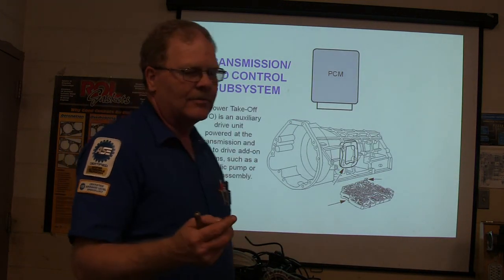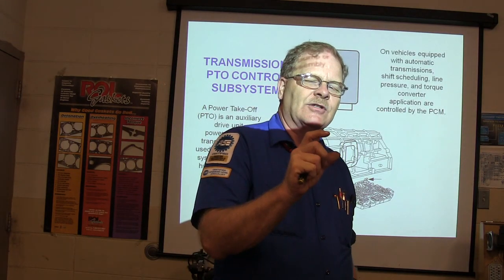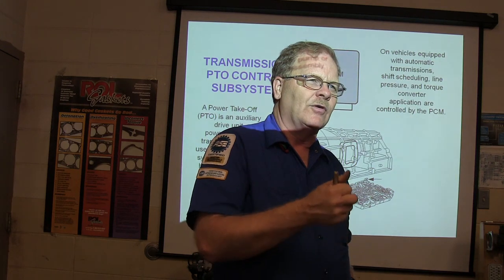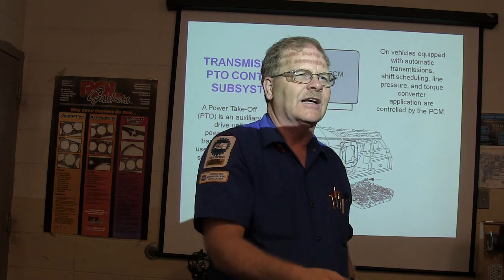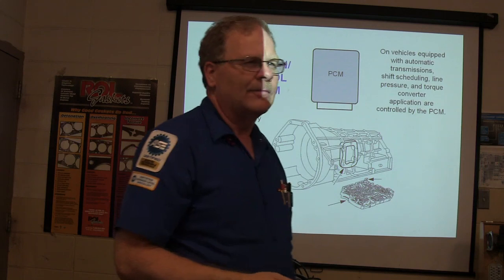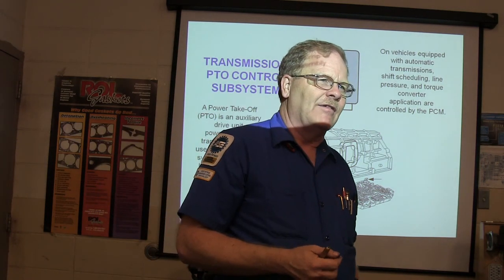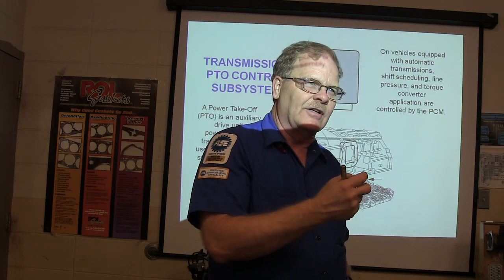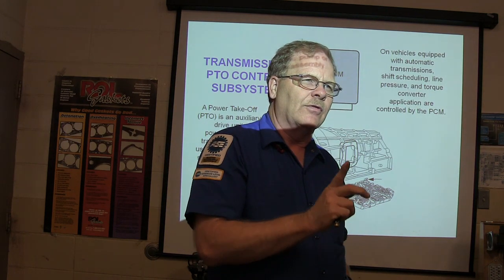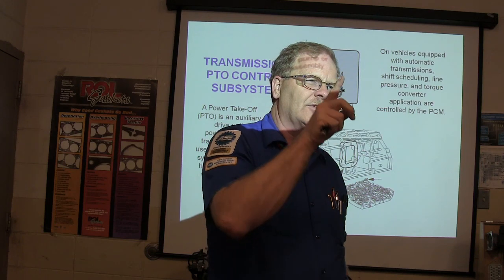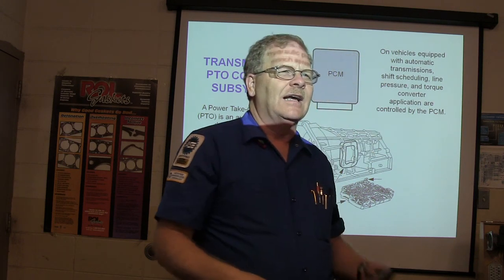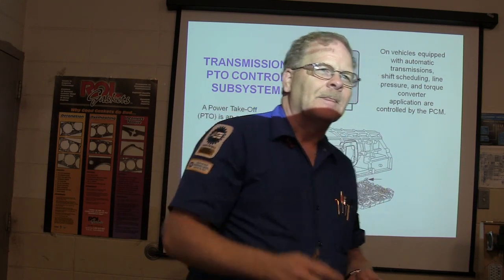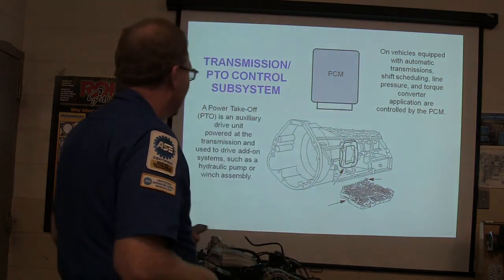Also, sometimes those little brake pressure switches will start to leak, and whenever they start to leak, they'll actually push fluid through the wire harness, and it'll get into other connectors and short things out. General Motors eons ago used to have engine coolant sensors that would leak. Those sealed connectors had seals in there, but the coolant would go through that sealed connector, and the pressure would shove it through the wire, and you start having all kinds of problems. You pull the engine controller out and pour antifreeze out of it, because those engine coolant sensors do that.